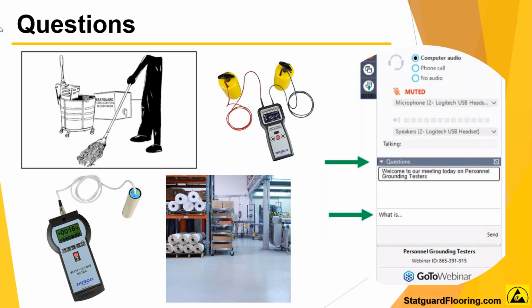With a permanent flooring solution, that would be maintaining it, removing dirt or debris that's building up and increasing the resistance of the floor. Permanent flooring is not going to go bad if it's installed correctly. It's not going to go bad, but you do get that dirt and grime buildup, right? Correct. That can raise the resistance. Yeah. So that's why you would still want to test some of those key areas that you feel are high traffic, a lot of walking. Higher resistance, right.